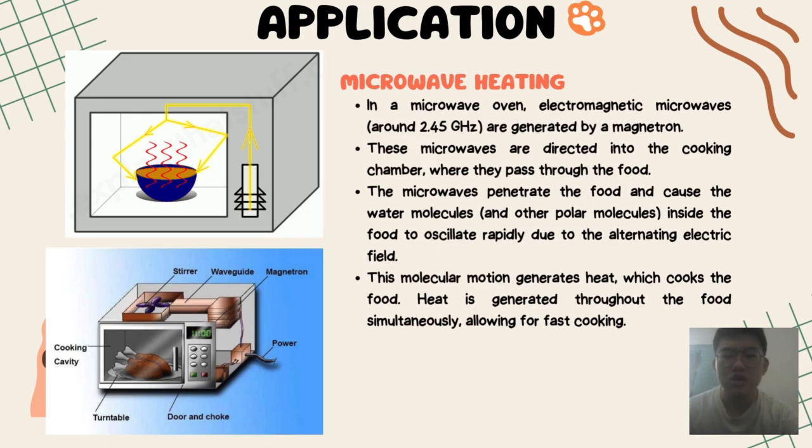When a high voltage of around 4000 volts is applied, the cathode produces free electrons, which give up their energy to produce the rapidly oscillating microwaves and direct them to the waveguide by electromagnets. The waveguide reflects the electric field internally and transfers it to the heating chamber.